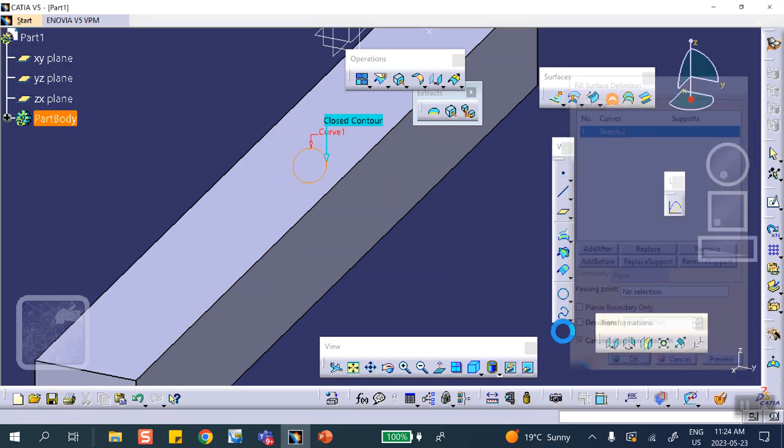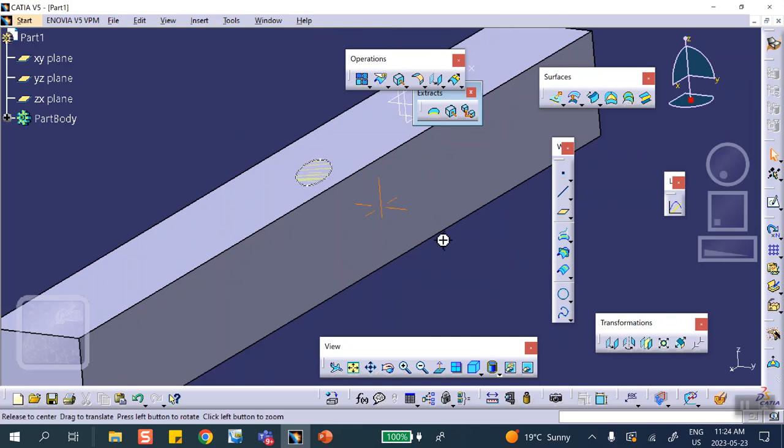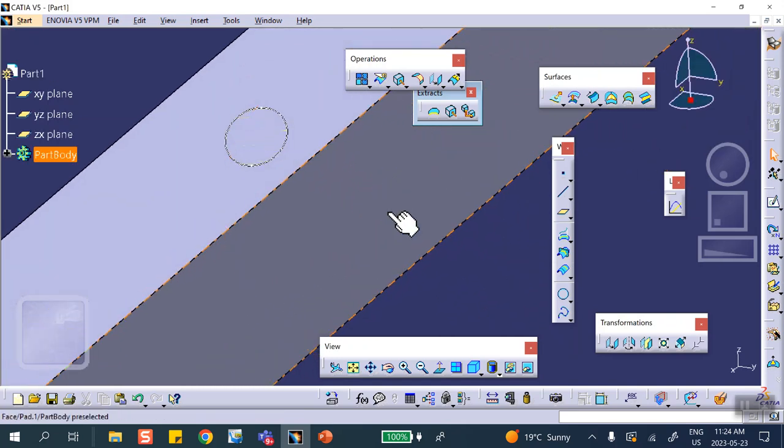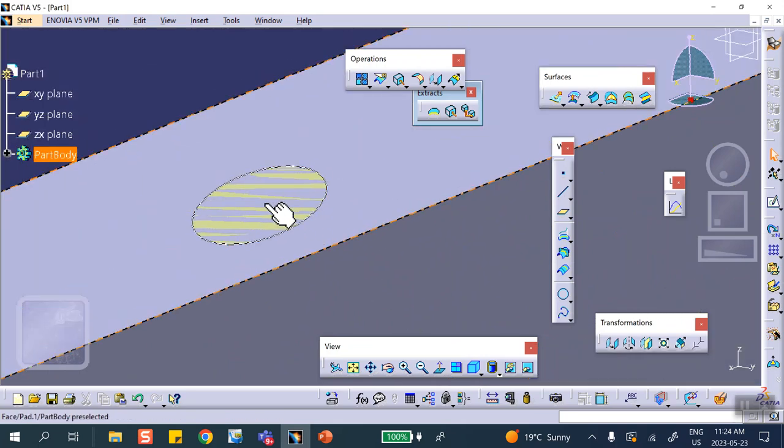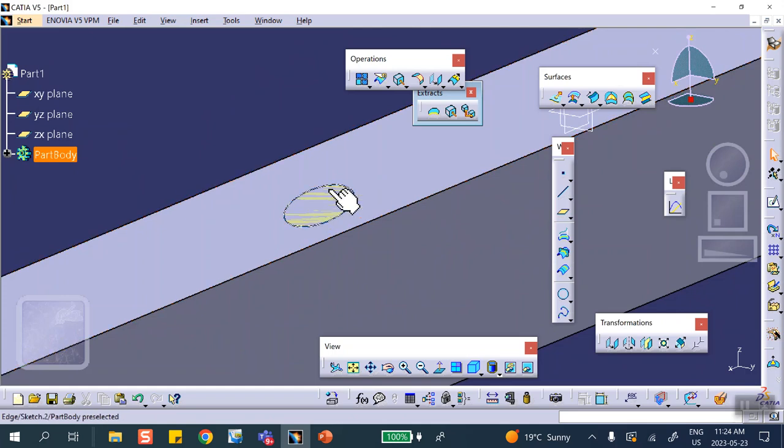You say okay. Notice that it did put an ivory looking color here. You can see that right there. So a patch has been created here, but that's not good enough. We have to sew this patch, or sew the surface, into that object. As soon as you say sew it into the three-dimensional object, you have to go back to part design.